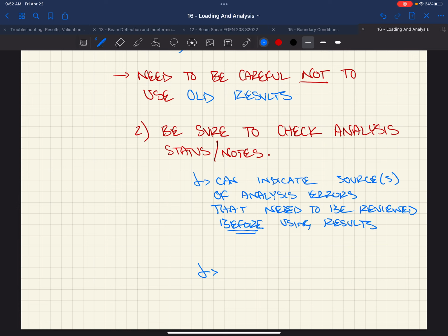One of those examples that Adam brought in was where that guy had 7 light years of displacement, right? It said in the error that they had excessive displacement, and they did not look at it. Some of those are the big ones. VA will say, okay, the overall model size is 100 feet by 100 feet. If it gets a displacement that's more than like 6 inches, or maybe even like 3 feet, it knows that something's wrong.